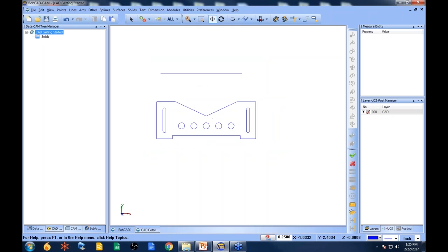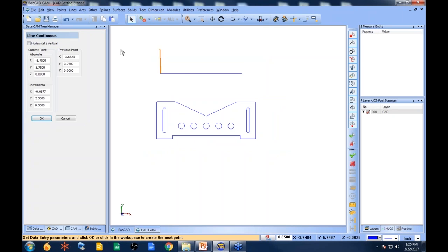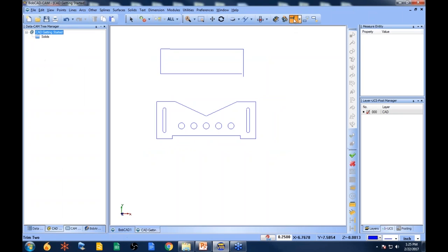Well, the way that this works here is, if I chain this up, let me just draw a chain around this, and I'll trim these together. This is a big reason why you choose chain selection versus window selection. There's no way for me to select just that entity there if I didn't know it was there. There's just no way for me to really do that. There are no tools within the software for that.